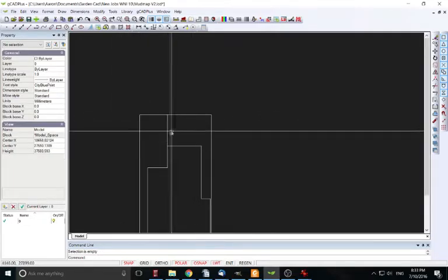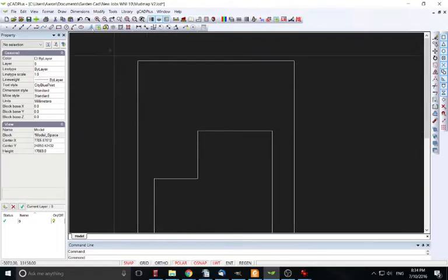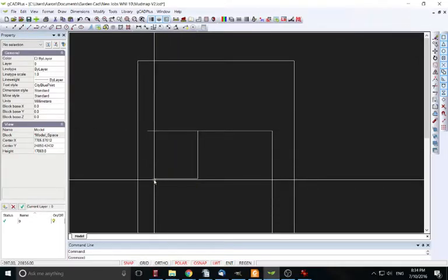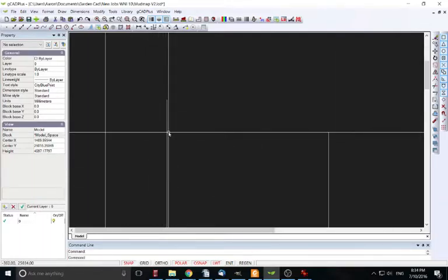So already there, we can delete this line, erase that, and we've still got to get a post in here. 1 meter out, we'll use the point tool this time. Well, actually, again, it's easy to just use the line tool. Snap on the corner there, out there, escape, enter, enter, and out there. And so I didn't write down the measurement for this.